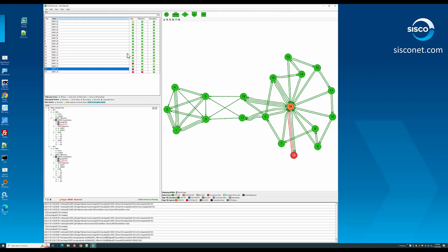Goose messages are multicast messages. They're not acknowledged, so sometimes they get lost. That's expected. It's baked into the protocol. We have a retransmission strategy. So sometimes we'll see a transient fault. When that happens, we latch that so that you can still see it in the logs, even after it is cleared and the current status is good.